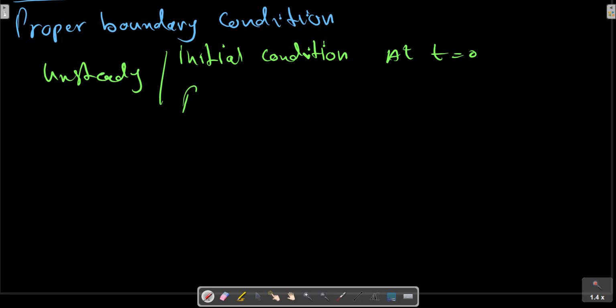We have rho, V, p, internal energy and T as a function of spatial value for the 5 flow properties. Therefore, for all times t to be analyzed, we must know something about the variables at each boundary enclosing the flow.